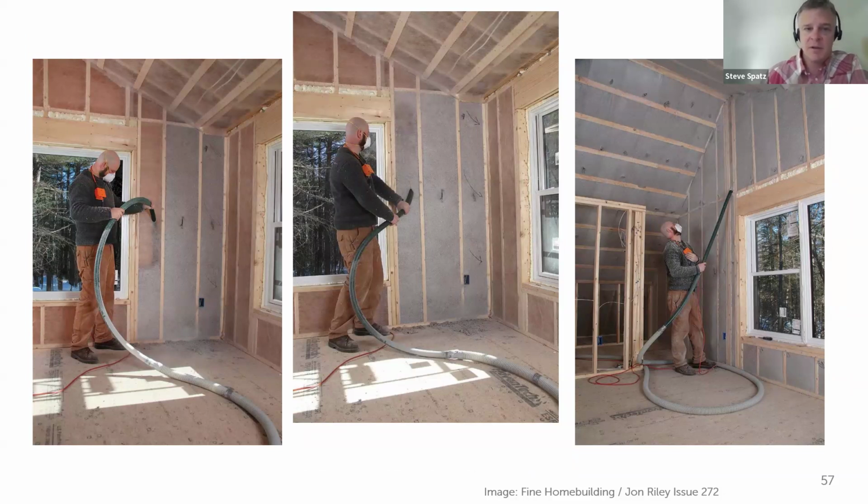So it can be challenging to get to proper density when using some of those materials. So often, when dense packing before an interior vapor control layer is put up, just blowing behind this InsulWeb or netting is the effective way to go about getting your proper density in these assemblies.